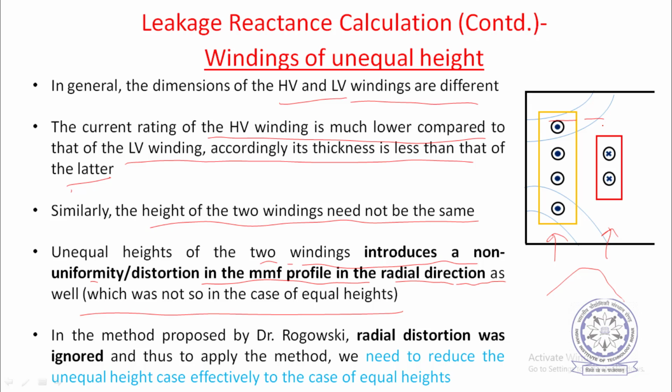Of course, the resultant MMF is non-linear and is the resultant of these two directions, one is the axial direction and the other is the radial direction. So the flux lines are different, but you can study these two components, and then the total energy can be calculated by summing up the individual energies of these two perpendicular components, that is, the radial component and the axial component. So we will see radial flux and axial flux, or radial MMF and axial MMF, and then finally the total energy can be calculated independently, individually, and then summed up. That is possible. That can be proved theoretically also.